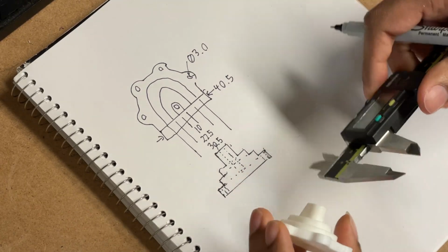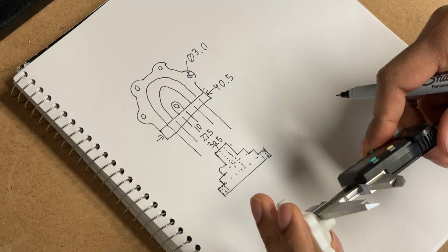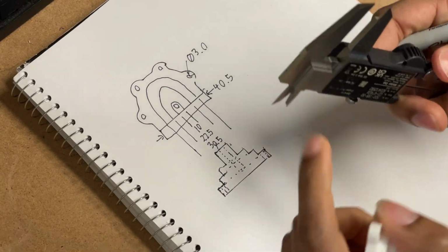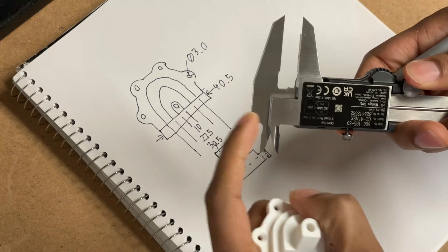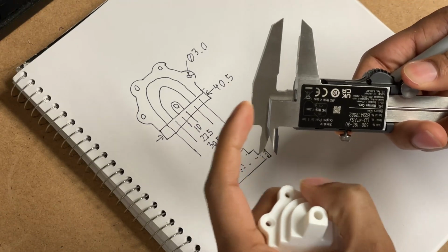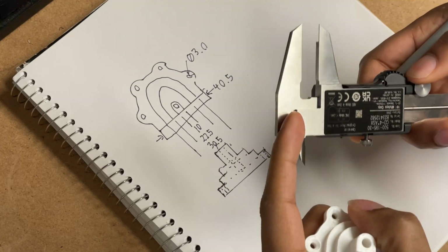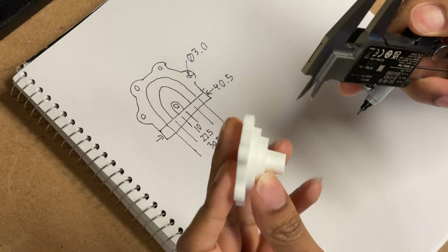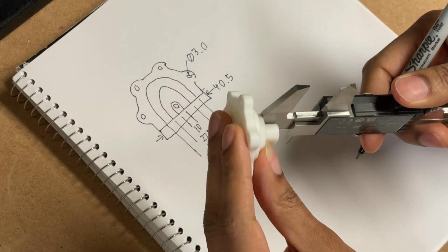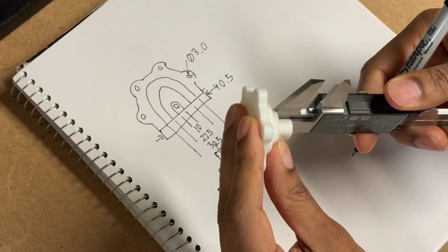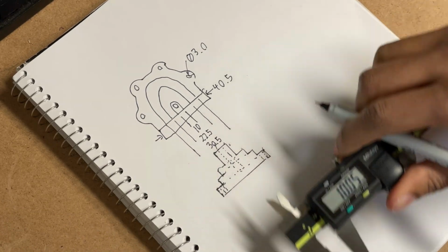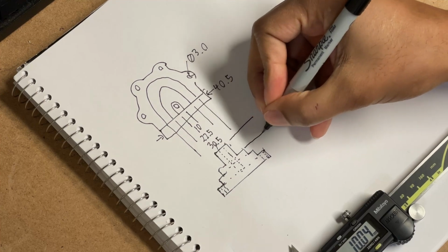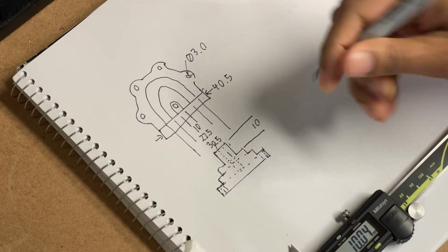Okay, maybe now I'll start to measure some of these depth measurements. What about this one? Here I'm using this back face, you see? So this measures the distance from this face to this face. So that would be 0. That would be something else. This is a step measuring feature. Very useful. There we go. This step here looks like it's 10.